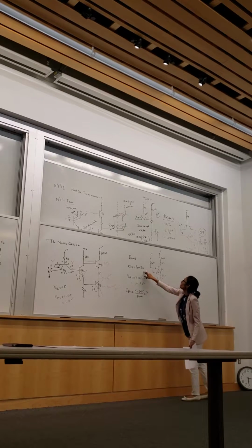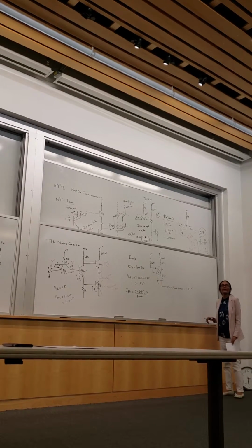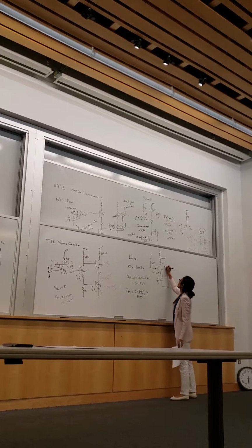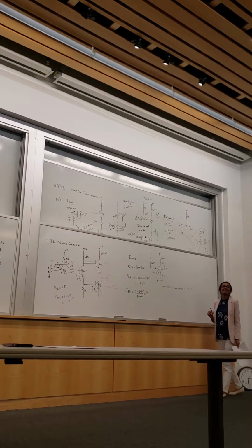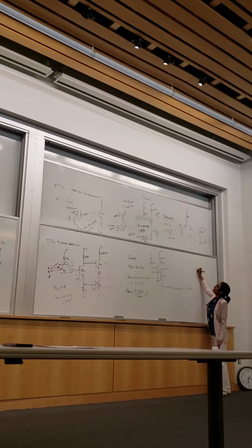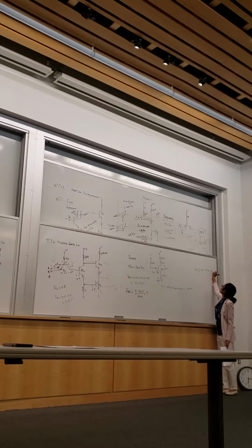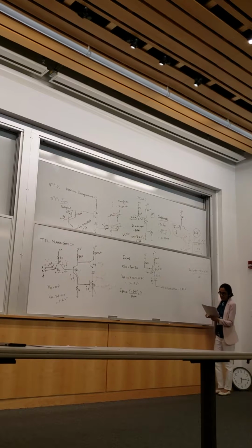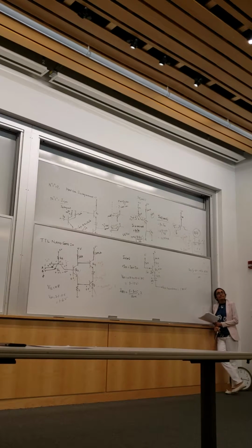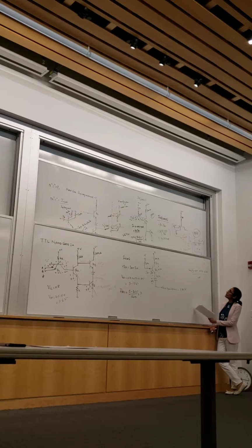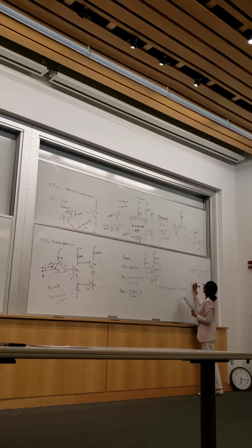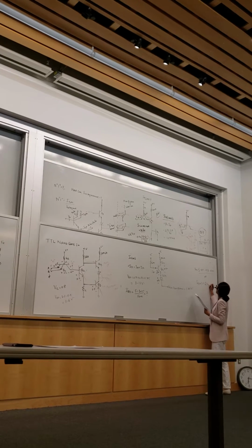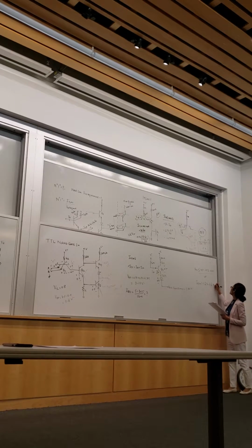Now, IC4. Is it beta 4 times IB4? This transistor is in the saturation region. What's the drop across it? 0.2 volts. So IC4 is going to be 5 minus 0.2 minus 0.7 minus 1.75 divided by 100 ohms. Good. Now just add these two values. I believe my calculations are correct. That's going to be 24.66 milliamps.